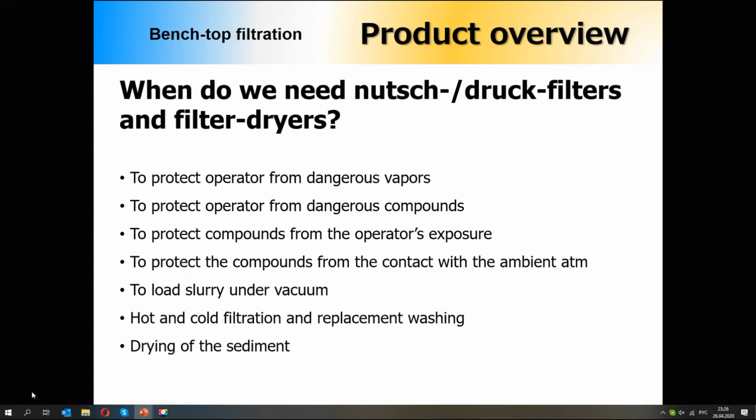It is very easy to operate with a funnel when the funnel is relatively small and the volume of the reaction mixture is relatively small, like 100 mils or 200 mils. But when we're talking about 10 liters or 50 liters or even 100 liters, you cannot just take a flask with your hands and rotate it above the filter and discharge the flask straight onto the filter, because